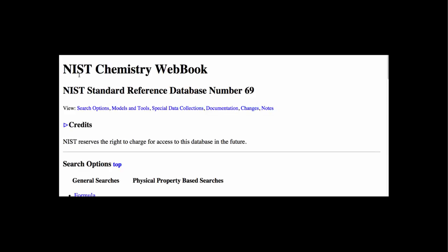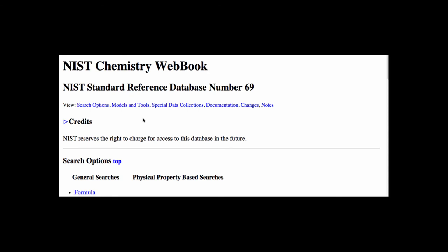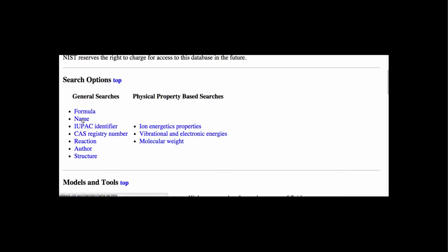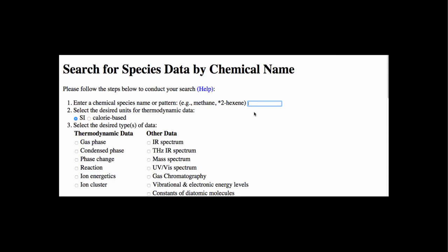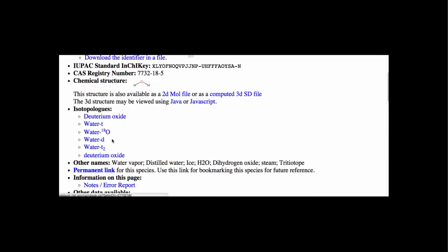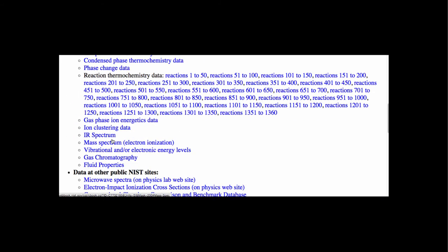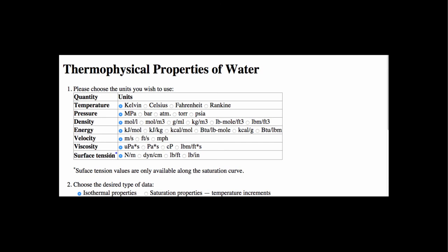All right, so now that we have that, let's look up what these numbers are for water at the National Institute of Standards and Technology's webbook. So just Google NIST webbook and you'll find this pretty easily. Put the name of the compound, so we just want to look at water. And we want fluid properties. And we'll use units of kelvins for temperature, bars for pressure. Everything else in here looks good.